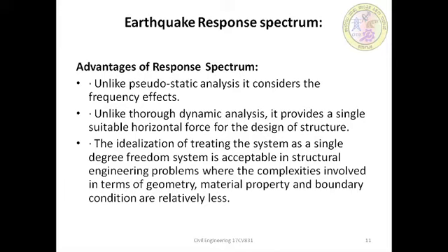What is the advantage of the response spectrum? The response spectrum has been found very important in structural engineering since the inception of the response spectrum method. The analysis has advantages: unlike pseudostatic analysis, it considers the frequency effect, and through the dynamic analysis it provides a single suitable horizontal force for the design of the structure.